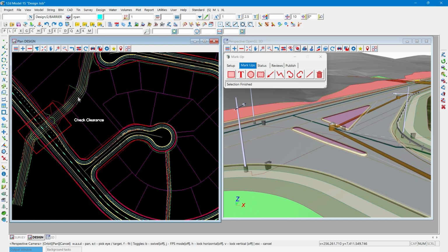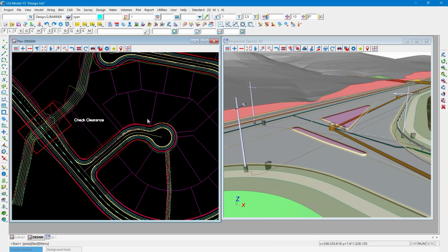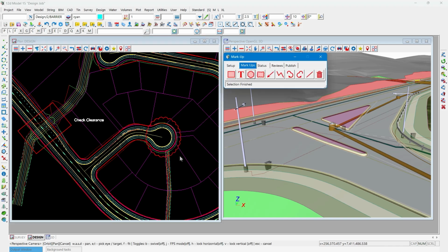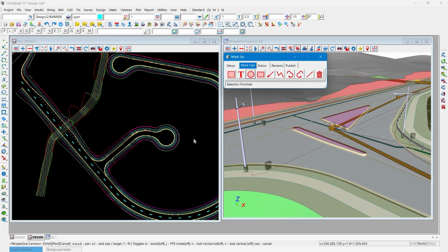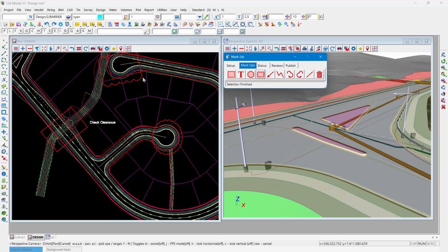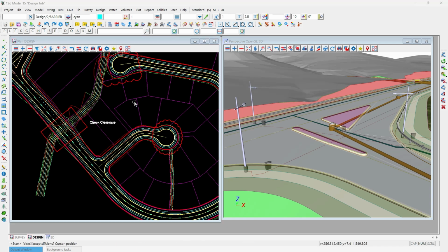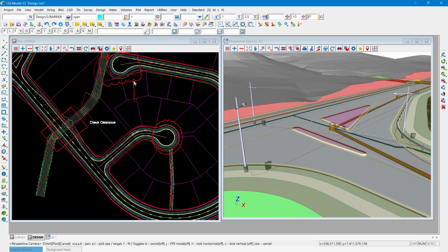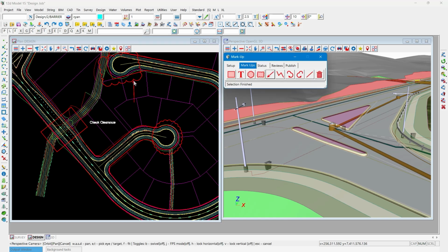Your more traditional revision bubble is the third one along, so I can draw my revision bubble. You can have a rectangular revision bubble as well. Again, it's a rectangle, so that's 3 points it's requiring for your rotated rectangle. And if I want to draw my attention to a particular point on the screen, I can just use a pointer or a pointing arrow and maybe have some text placed on the end of that.